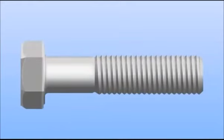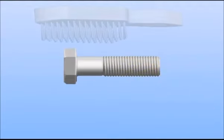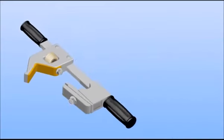If the fastener is reusable, there are a couple of things to note when determining the condition of the threads on a fastener. Never install a dirty threaded fastener. The dirt will increase the friction between the threads and cause the fastener to be mistorqued. If the threads are dirty, use solvent, a wire brush or wheel, or a thread chaser to clean the threads.